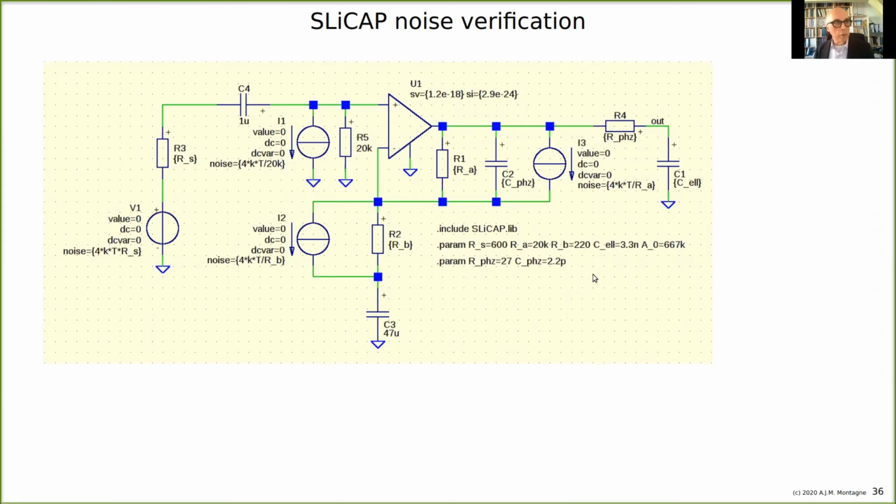So this is for the noise verification. And we find 2.4 dB noise figure if I assume 500 kilohertz bandwidth multiplied by pi over 2, which is a noise bandwidth if it is first order. But that's an estimate, because I think the thing will not be first order, of a little bit more than 500 kilohertz, pi over 2 times 500 kilohertz.